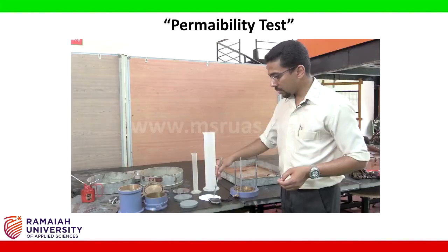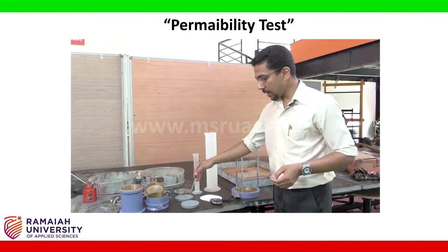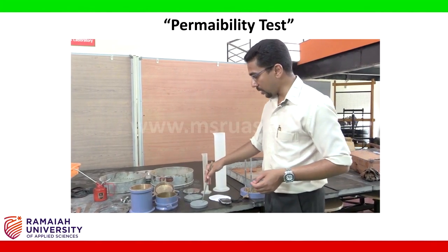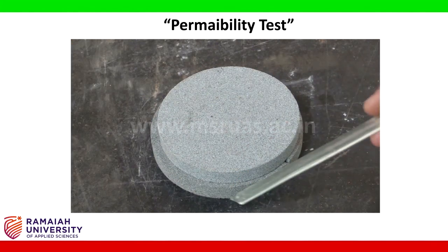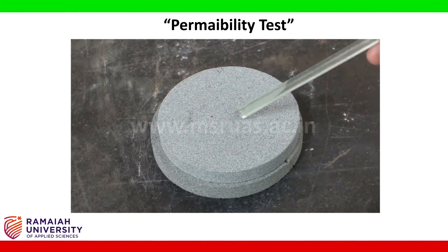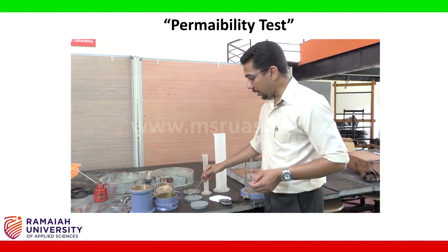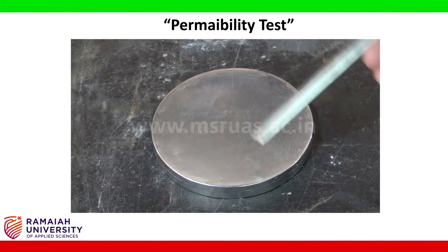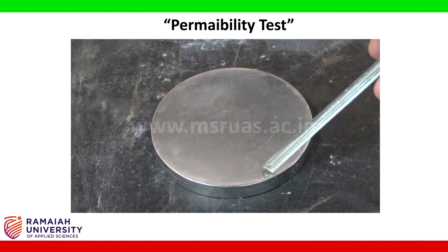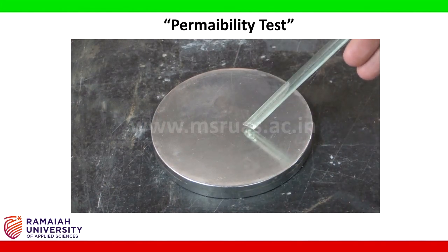the test process. The bottom porous plate, top porous plate, these are the two porous plates that are required to be placed at the bottom and at the top of the specimen to be subjected to this particular test. The base plate required for compaction, the steel plate of 100 mm dia, which is required to be placed in place of the porous plate during the compaction process.